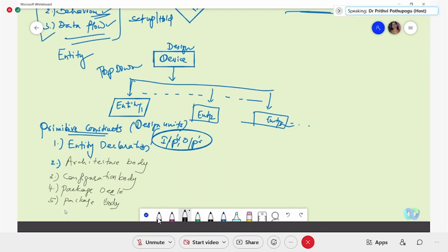What exactly are these things? When you are defining the total design, any design you take, either a top design or a sub-segment, each segment is called an entity, and each entity will have its own inputs and outputs. This is something like your full adder: if this is a bigger or top entity, you define its inputs as A, B and CI minus 1, and the outputs will be sum and carry. This is the single top level design.